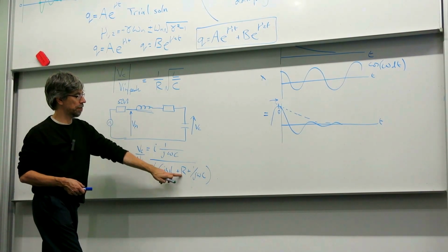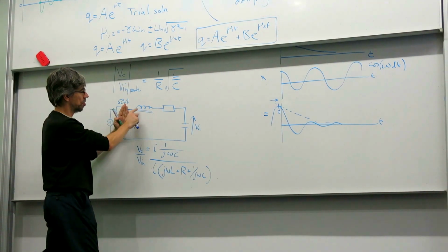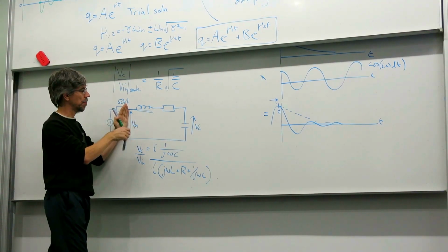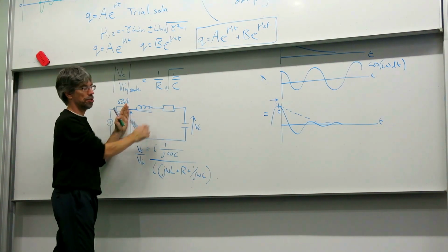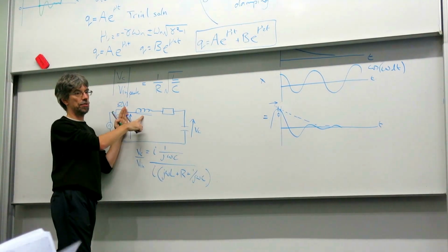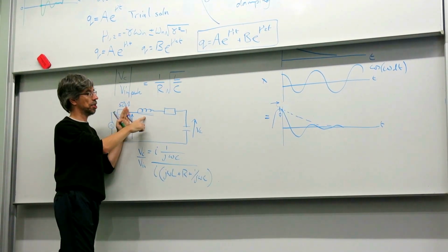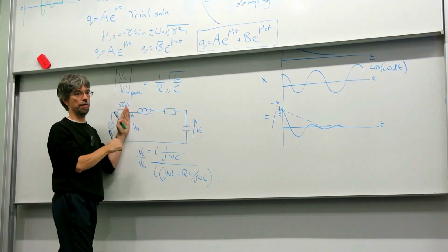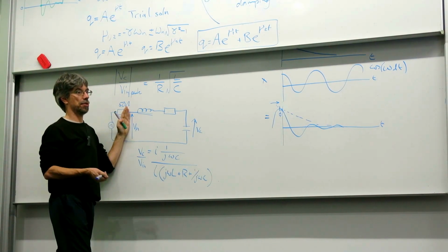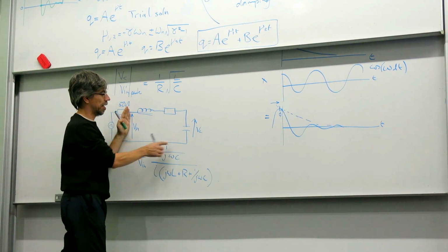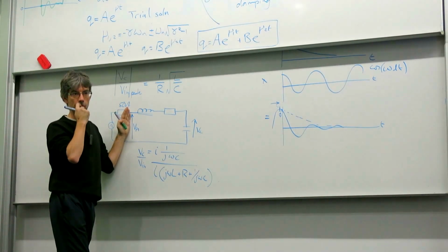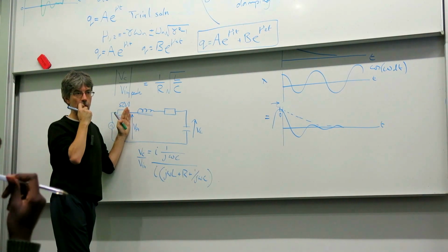But this R was the total resistance to the right-hand side of Vn. So it will be equal to the resistor box if you've got one set, plus any resistance in the inductor. That doesn't mean its impedance, it means a parasitic resistance that shouldn't be there, but is. And then any slight resistance in the wires. Capacitors don't have resistance.